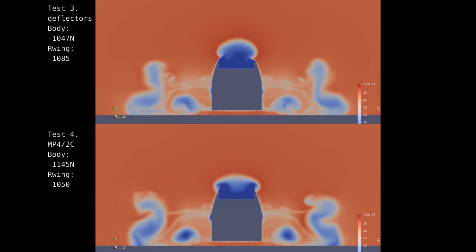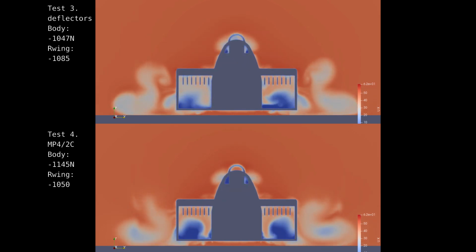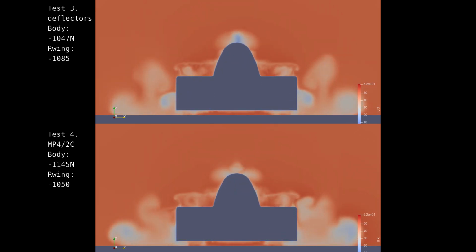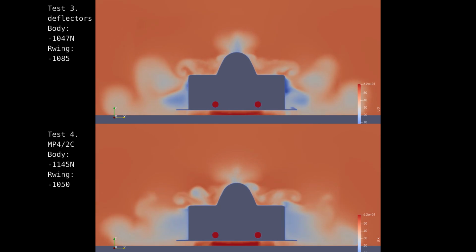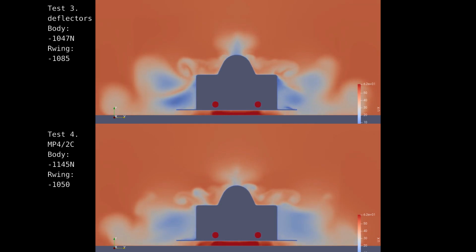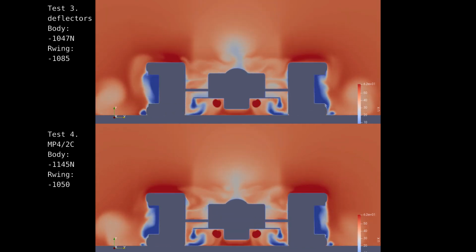For the last two runs, I pulled out the X velocities for the X-axis to contrast the pressure maps where the air is accelerating to create the high and low pressures. These maps show the resultant velocities from this acceleration, or its integral to be more correct. For an example, I paused twice, just inside the Coke bottle tapering and at the rear axle.